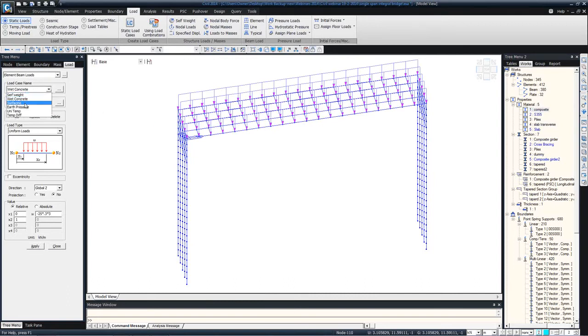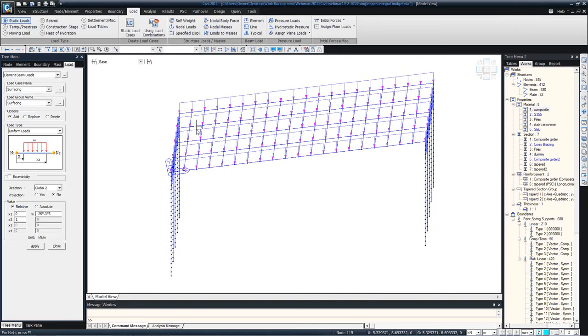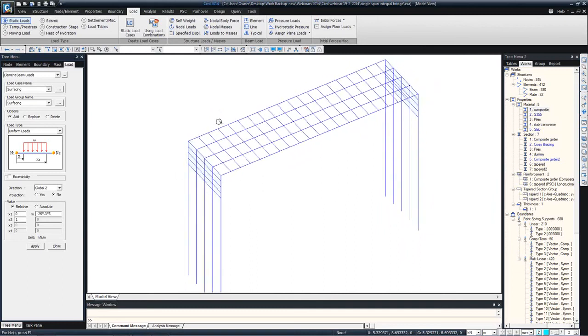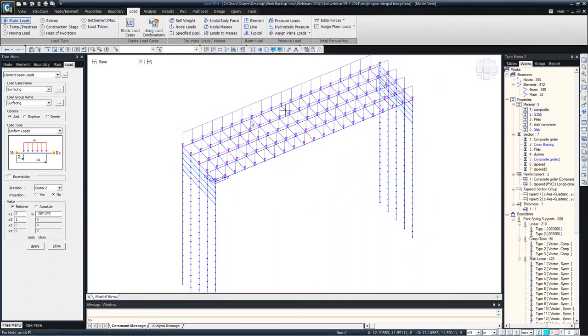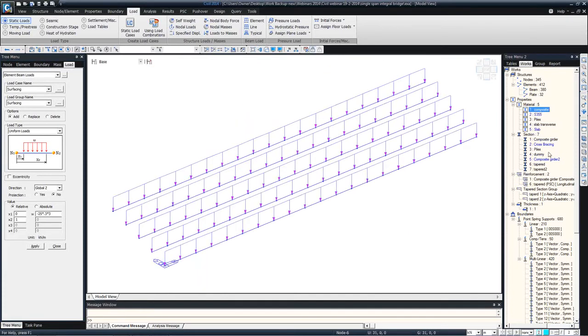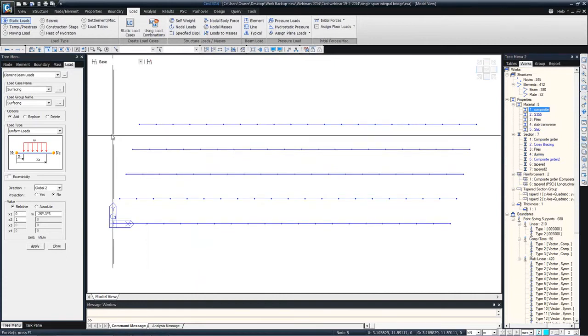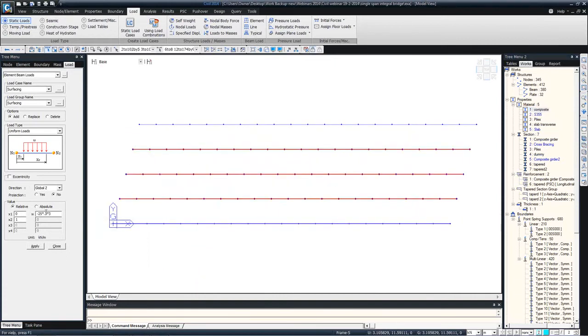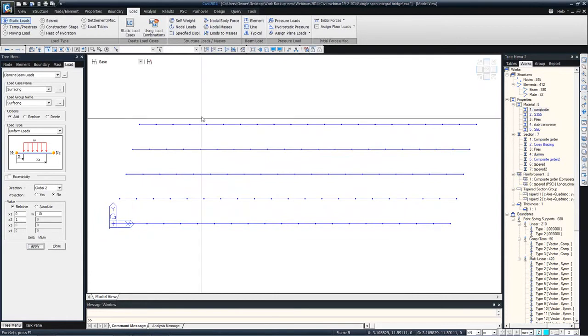The next thing is applying surfacing loads. So surfacing, we can select some of the internal beams and apply surfacing loads. You can apply surfacing as a floor load as well. Depends how you want to consider it. You can apply it as a UDL. So I'm going to apply it as a UDL in this example. So just selecting, say, these many girders and -10, for example, and apply.